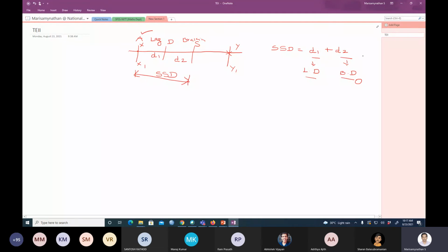When you add the two distances together, and the vehicle definitely avoids the collision with the opposite obstacle, that distance is defined as the safe stopping sight distance. Basically, the distance depends upon the reaction time and the speed of the vehicle.